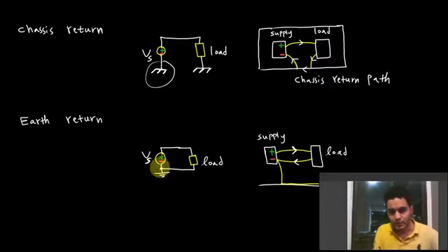If you want to basically not have a floating voltage, you want to have a common reference for multiple different circuits, you would need to ground. The negative terminal is usually what's used to ground. You could also ground it at the top, but that's going to give you ugly minus signs. You don't want to deal with that. So you just ground the lowest potential of your circuit, the negative side in this case of the source, and